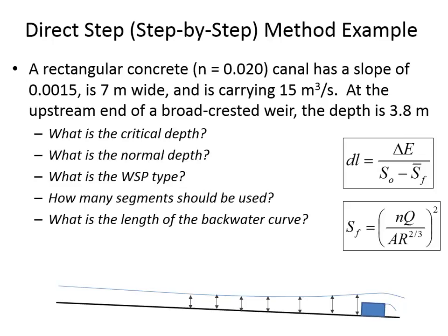That means that we should use 5.21 segments. In other words, we'll use 6. And each of the 6 that we're going to use is going to have an elevation difference of 0.43417. I just got that by taking the total elevation difference divided by 6.